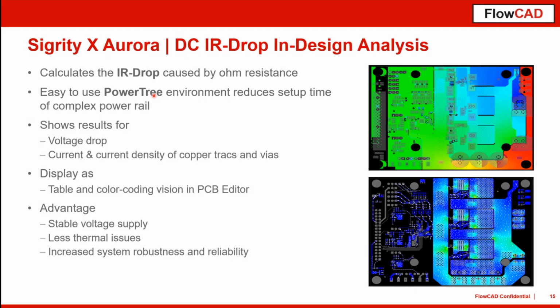So in this case, you can configure or model these discrete elements so that finally you will create a complete closed current loop from the voltage regulator to your sinks, or even to your loads. So it's very nice to work with the power tree.